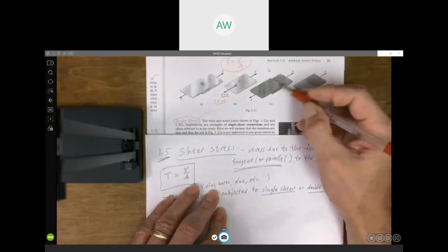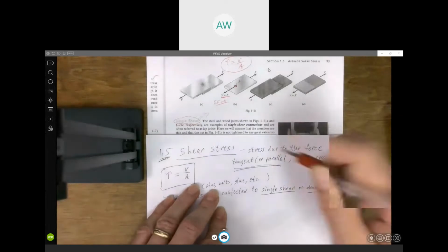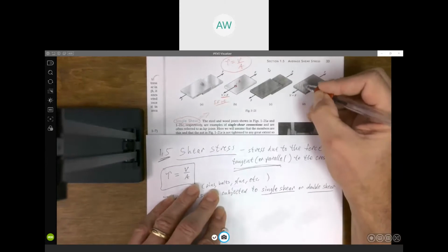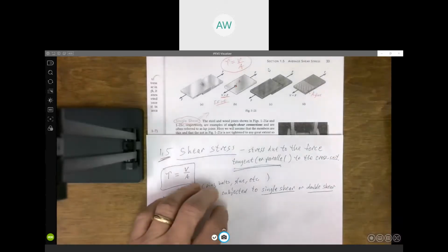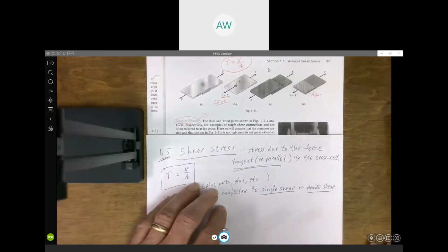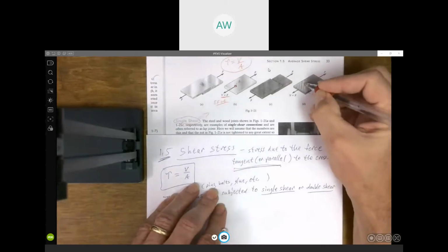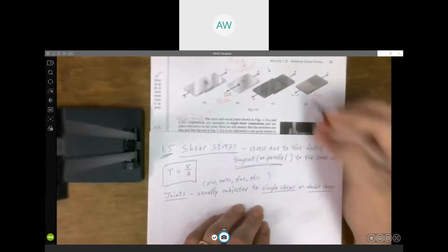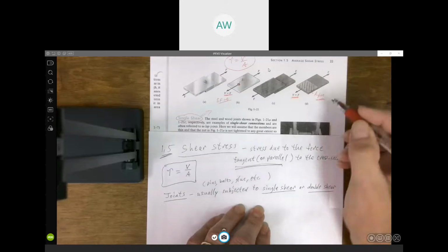You're looking at these two, actually looks like wooden boards maybe, but they're glued together. So rather than putting a bolt through there to attach these two things, somebody has covered some area, some part of those boards, with glue and stuck them together. So the same thing is going to apply when you're getting, let's say, the shear stress here on this cross-sectional area, the surface area of the glue. V would still be equal to F, but the area here would be the area of the glue,